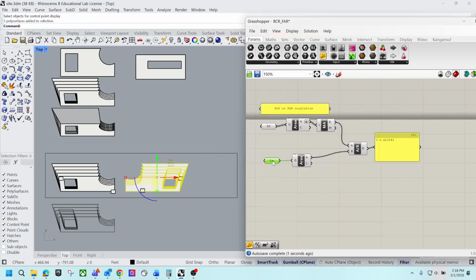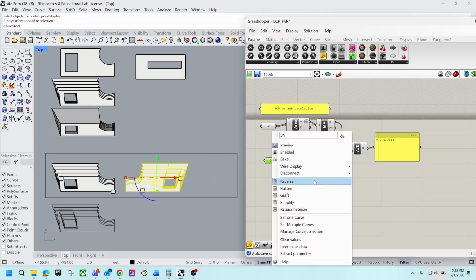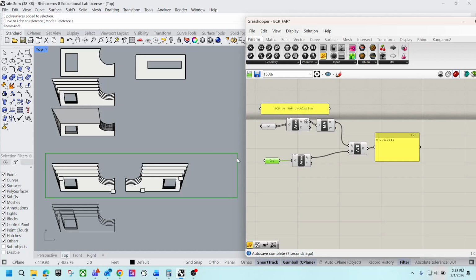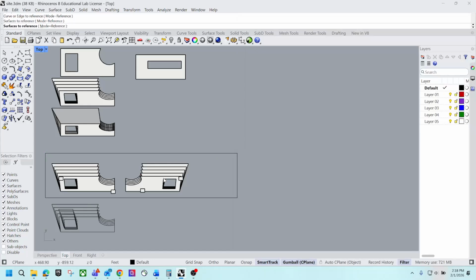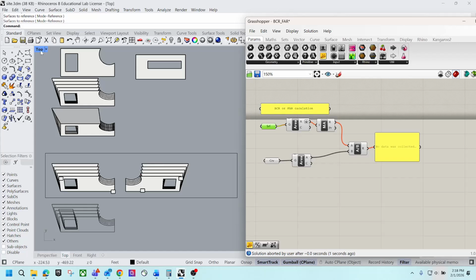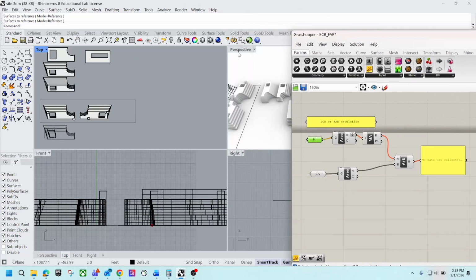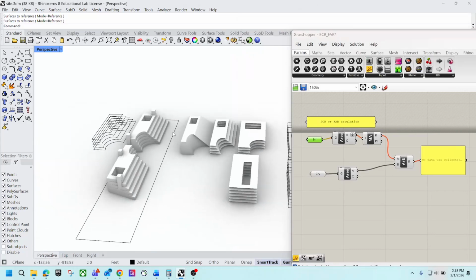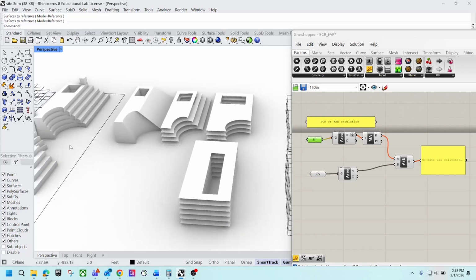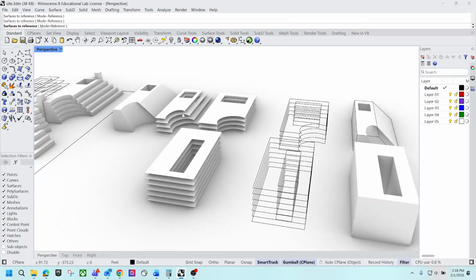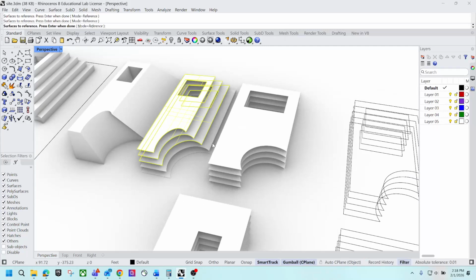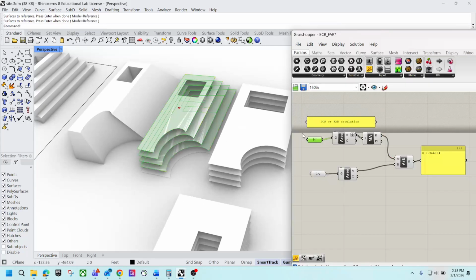So here, for the site, I will reset the curve to here, which is actually identical. For the surface, I will set multiple surface. Let me just make sure I'm selecting the surface, not the massing. Oh, this is a massing model. So for the curve it's the site. The surface, I will right click, set multiple surface. If this is your site, I can hold shift, select 4, enter, finish. So now you have this FAR value at 0.3.